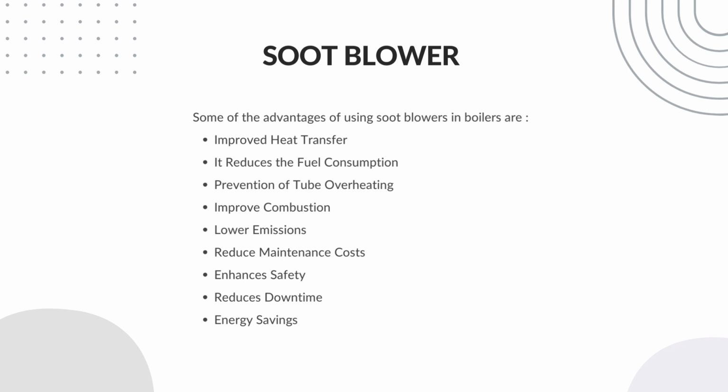Regular soot blowing helps maintain safe boiler operation by preventing dangerous conditions such as overheating and tube failure, which can lead to accidents. It reduces downtime. Soot blowers can be used while the boiler is in operation, minimizing downtime and ensuring continuous production processes. Now, next is energy saving. By improving boiler efficiency and reducing fuel consumption, soot blowers contribute to energy saving and a more sustainable operation.